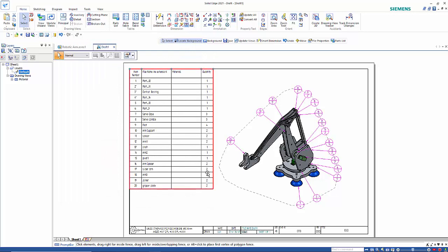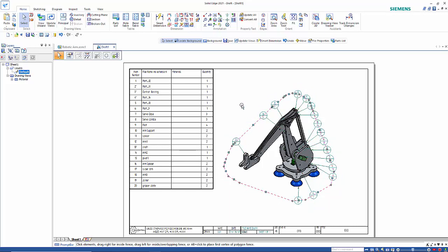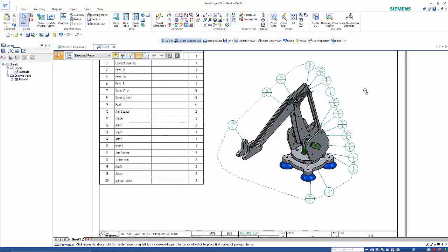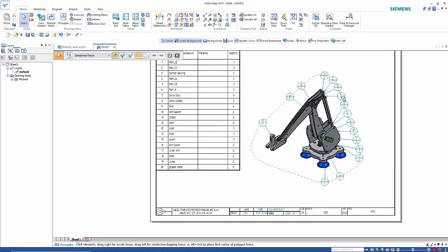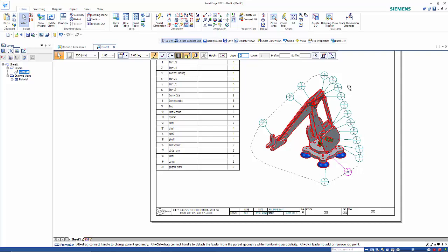Okay, so that will update. You can also see that on our item number we've got quantity as well. That's obviously able to be changed. The balloons are all linked to a chained item here, obviously not displayed, but it does give you the ability to move them all in the way that you want. And obviously you can just pick up on here and move these around to space them if you want to adjust that.